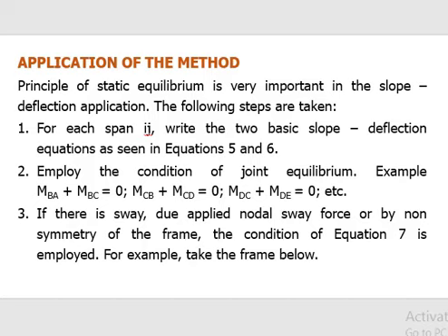MCB plus MCD must be 0. MDC plus MDE must be 0, etc. That is, the moment at the left hand of a support plus the moment at the right hand of the support must always be 0. That is one of the compatibility equations, or I can call it the condition of equilibrium.